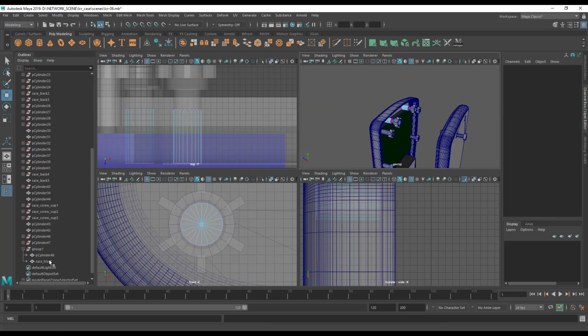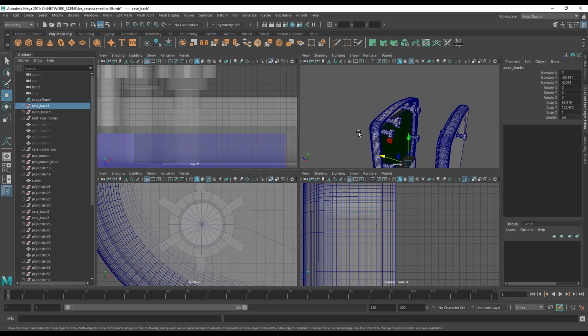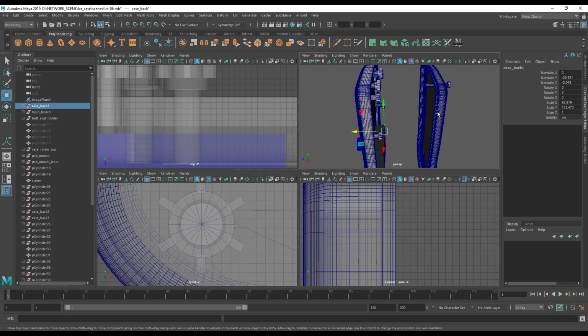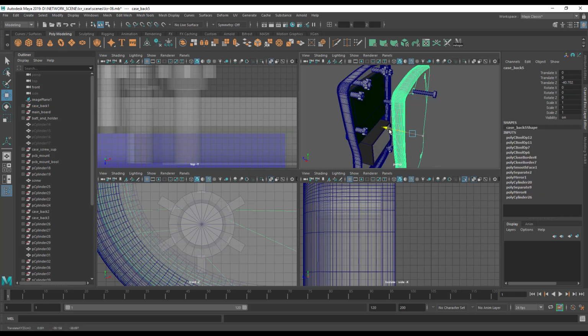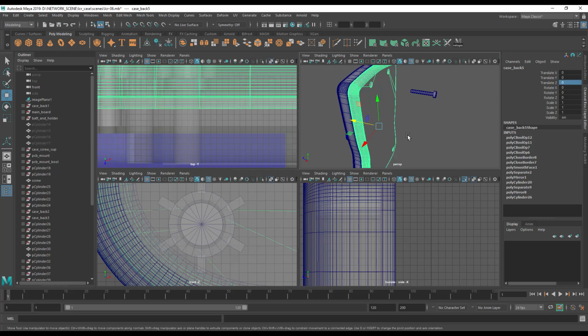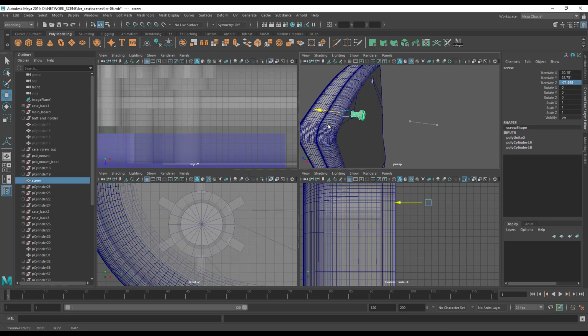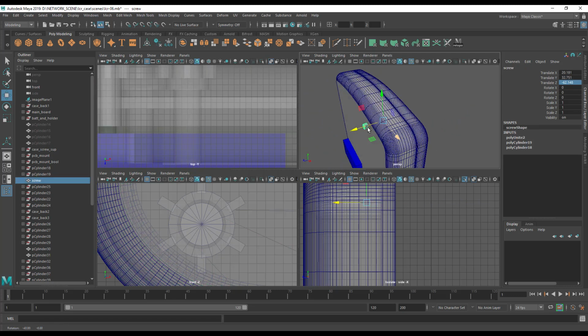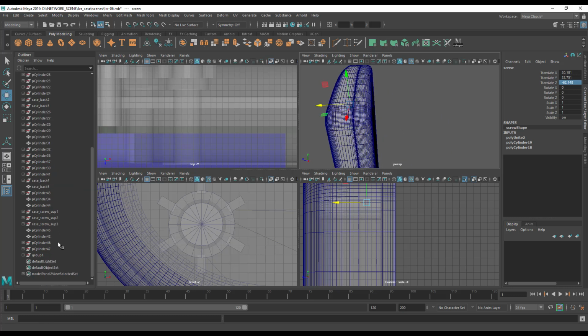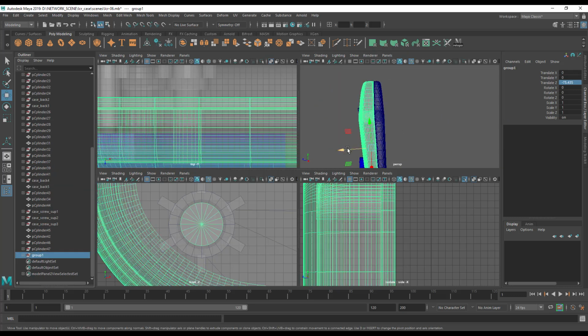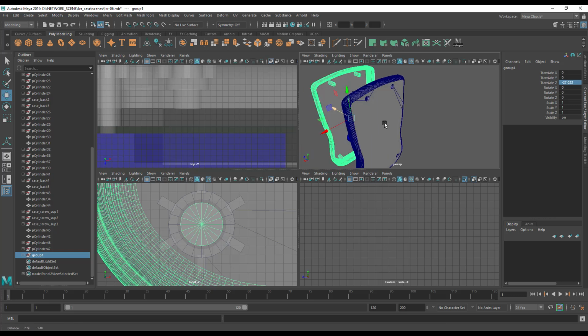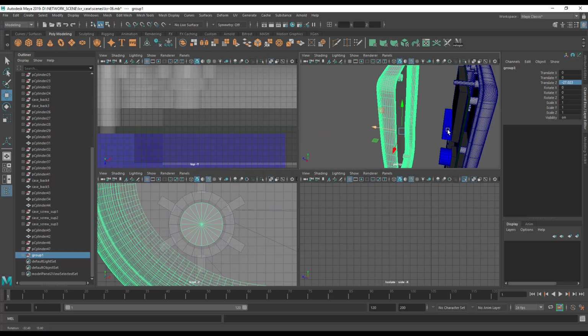Alright, now I can bring the case back, which should be up here. Okay, there it is. I actually didn't hide it. So as soon as I move this to 0, everything should line up in its proper place. Now we'll be able to put a screw through here, and it will be received into the head there, and it will screw into the plastic on the front here. So let's take this group and move it out. Okay, and we are done.